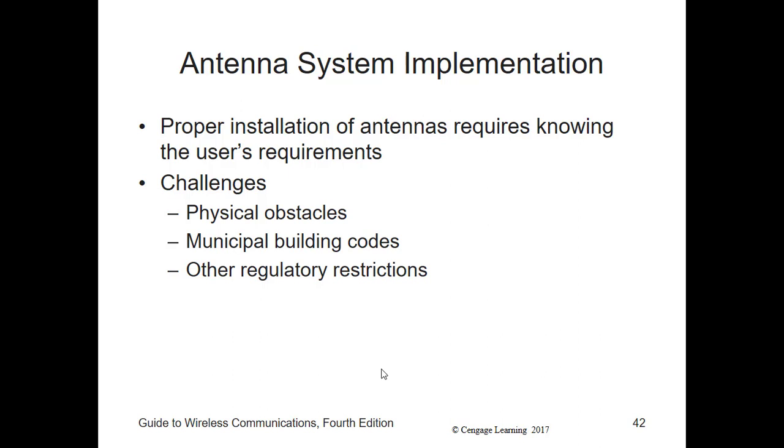Now, when implementing wireless communications, such as when setting up a wireless LAN, using the antennas that are supplied with the wireless devices limits you to placing the transmitters and receivers where you can achieve a good connection. If you need to go beyond the standard setup, however, if, for example, you purchase several different external antennas to ensure good signal reception in a difficult area, maybe for an outdoor link, there are a few things that you might want to consider. Most antennas are connected to the transmitter receiver using coax.